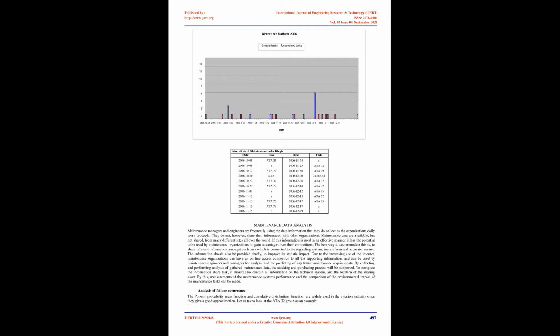The tasks were divided into 3 groups: scheduled inspections, special inspection/hard time components, and overhaul and life limits. All tasks in each group which shall be performed at the same timely interval are indexed together to minimize the amount of data. See Appendix I.